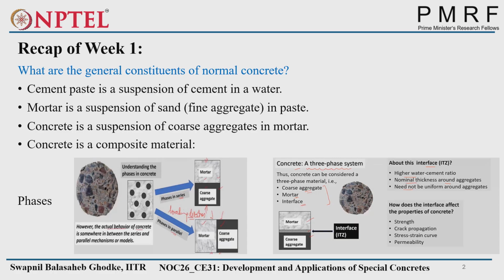That helps to reduce the cement content as well as helps to maintain the same flowability, right? Yeah. But the thing is that a certain amount of cement is there. You are saying cement content is also reduced, but still a certain amount of water is needed. Suppose at least 0.4 water cement ratio is required to get fully hydrated cement, and we are providing 0.3. So to get the higher strength of concrete, how will we achieve high strength? Still, the whole cement is not hydrating.